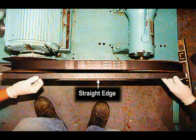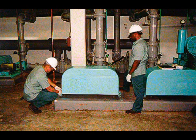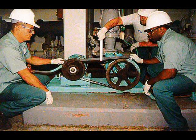Check the alignment of the motor and the belt sheaves. One method of checking alignment is to use a straight edge to ensure all points touch on the sheaves. With all the belts in their proper groove, the centers are adjusted to take up all the slack until the belts are fairly taut. Replace safety guards. Adjust the belt until there is about 20 millimeters or 3/4 of an inch of belt movement, or as specified by the manufacturer, from hand pressure at the middle of the belt.